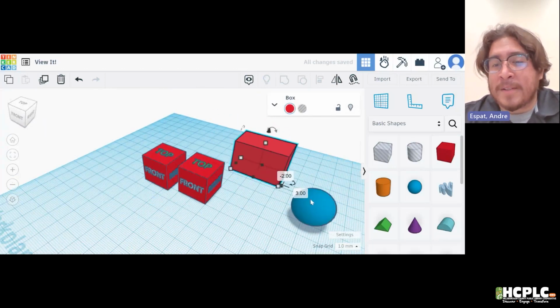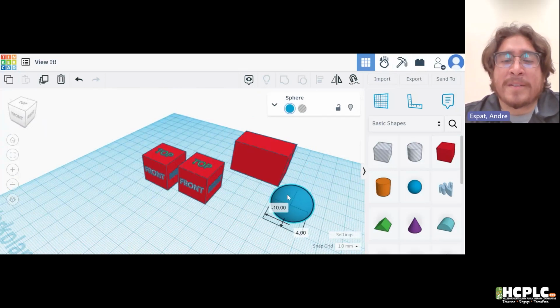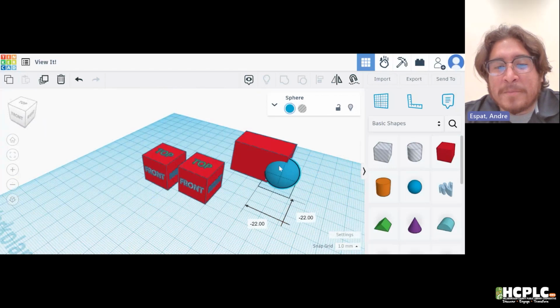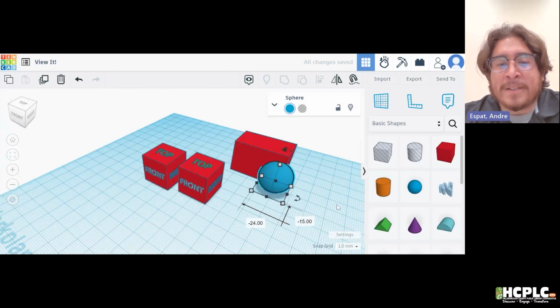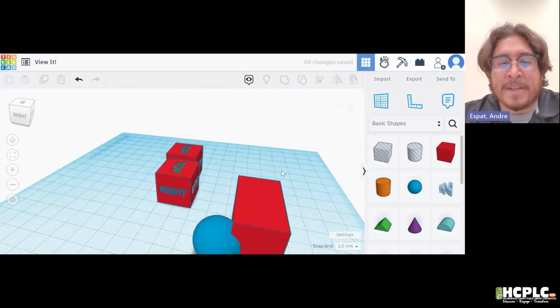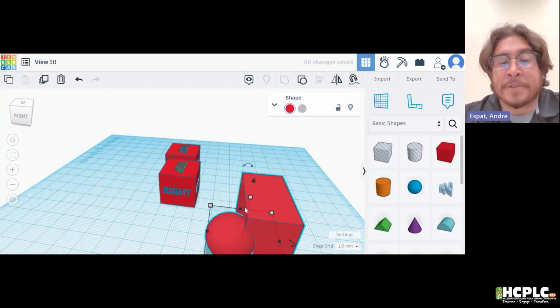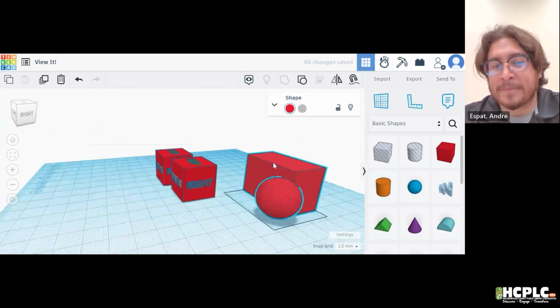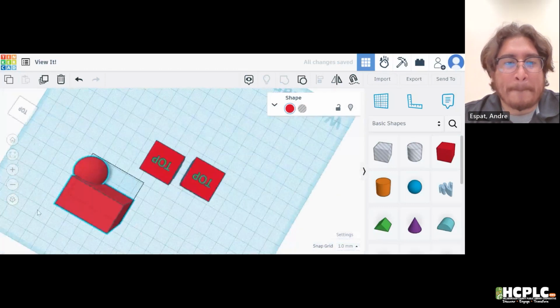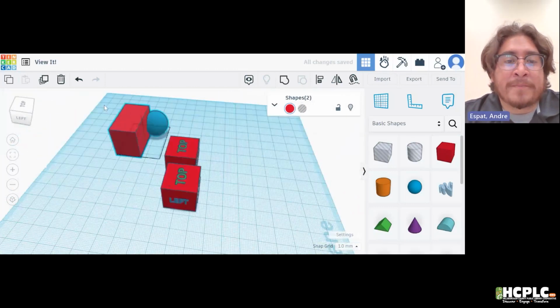An even cooler thing that comes with that, though, is that if I wanted to, I can just move this 3D object into here. You can kind of see that it's clipping through the rectangle now. If I wanted to, I can highlight both of them again and actually group them together, and now it's one physical object. Cool. I can ungroup them one more time.